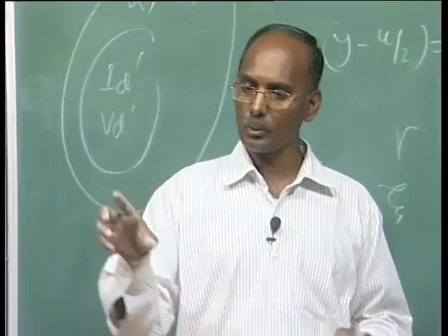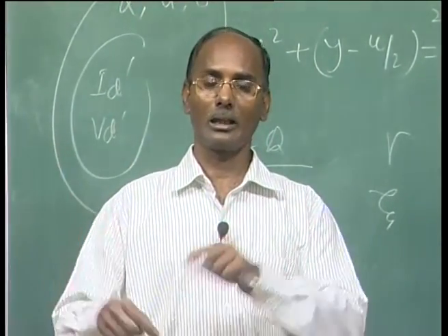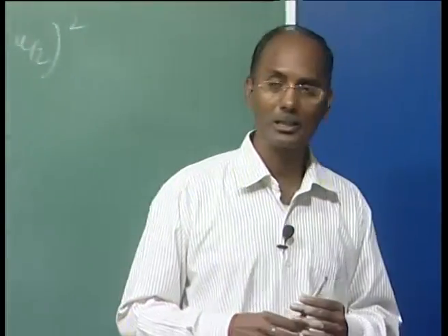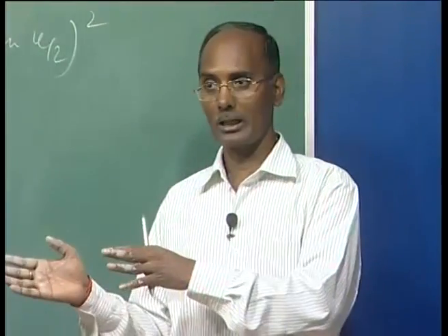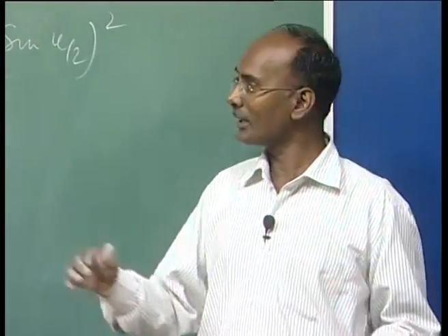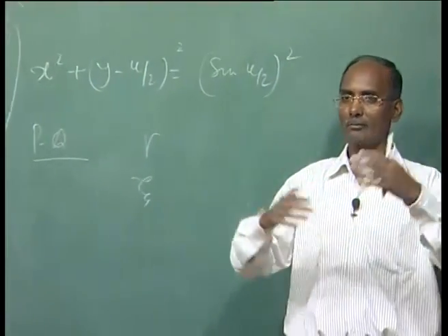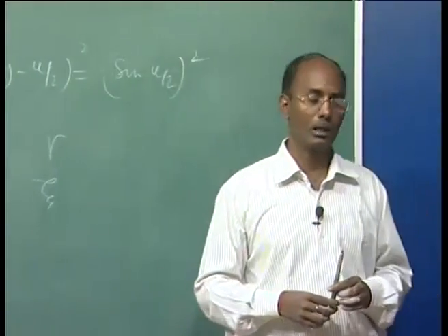First we try to control the voltage by the converter circuit. If the converter limit is hit, then the tap changer starts changing. So we'll see how this control philosophy is done and what the control characteristics will be for both rectifier and inverter side. One will try to maintain current, and there is the alpha minimum value, so many characteristics we'll find, and then we'll see what control schemes or philosophies are being used. We'll see that very clearly in the control operation.